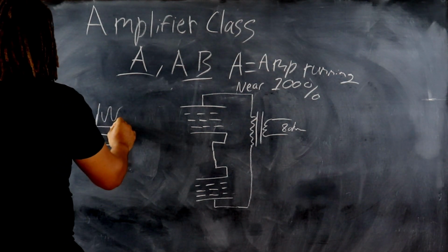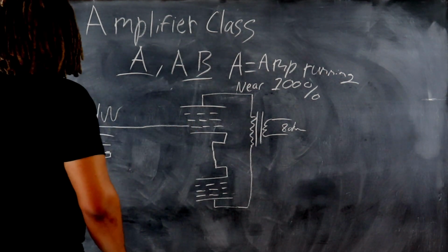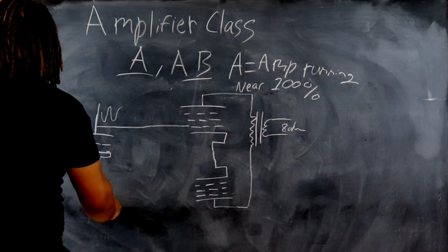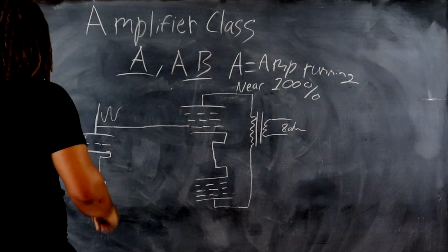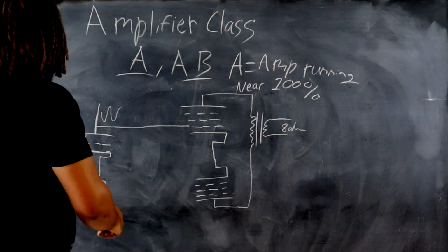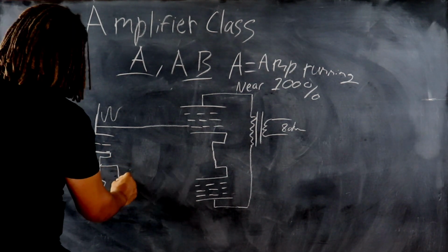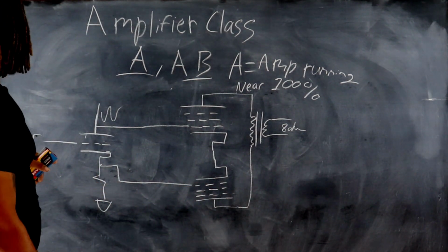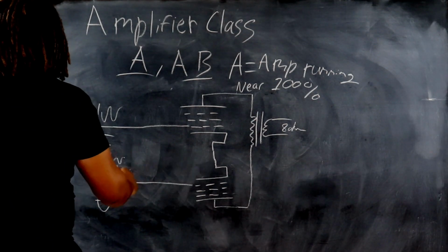So we're going to have this signal, and that signal is going to come up here. And then we're also now going to take a signal from the cathode. So we're going to get two signals out of that phase splitter, right? So we're going to take the inverted and the non-inverted out of here.